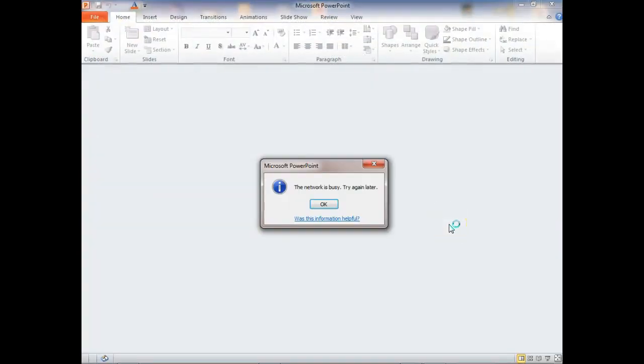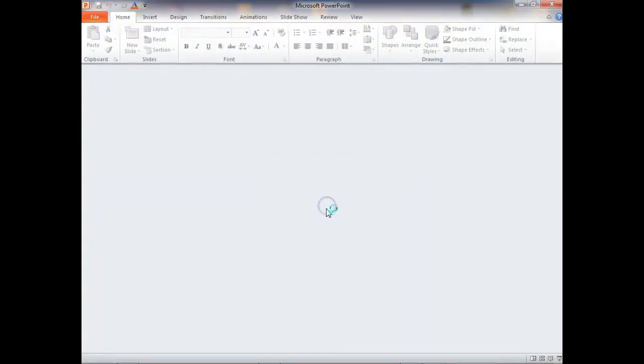And so we went back over just about all the stuff. Y'all got any questions about how we set up the computer? So if I hook up a new PLC, what's the first thing we need to do? Establish communication with the PLC. Once we've established communication, we open up a new program, some of them call it a project, by the way. When you get into Siemens, I think they call it a project. I think Allen Bradley calls it a new program. Then what's the first thing you have to do when you start a new program? Yeah, you select the processor.